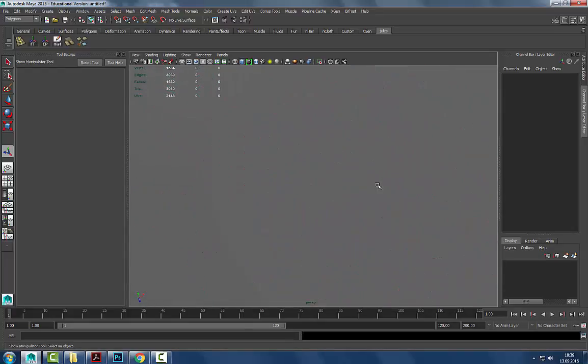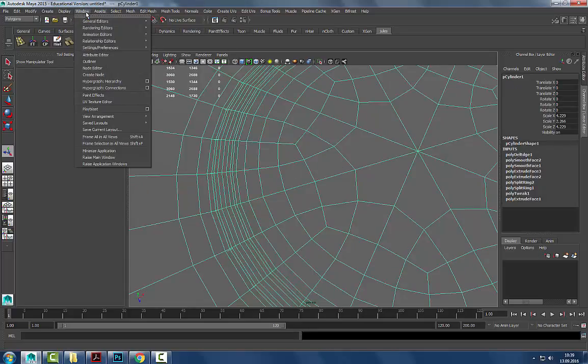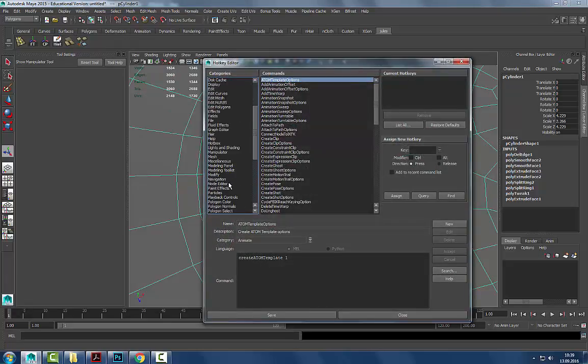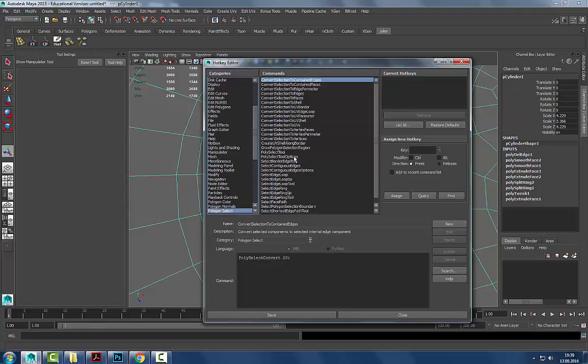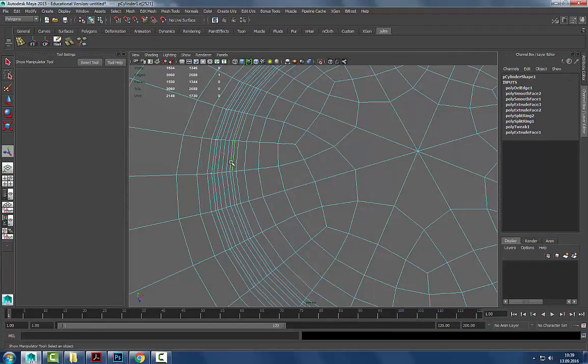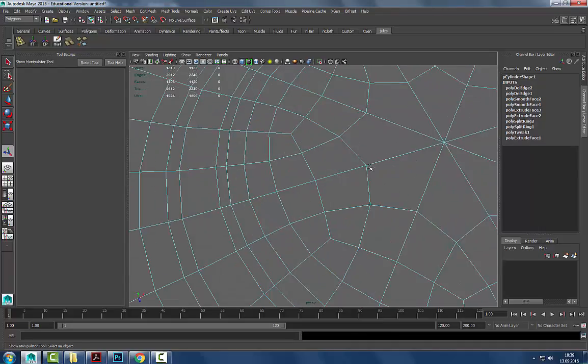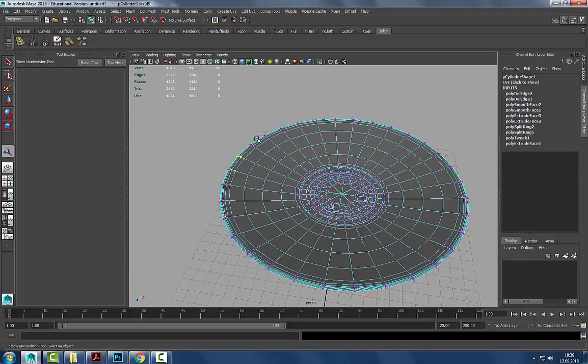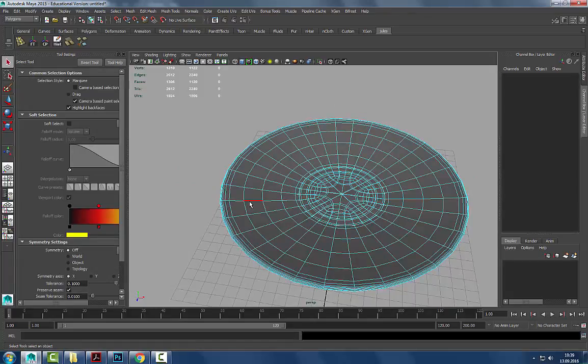This is totally nuts. So then all right, let's go to the hotkey editor, and then select, where is it, Polygon select. Yes, select edge loop. I'm going to do that on Control L. So now I have a hotkey. So if I do some of these, get rid of all these, I don't need the Control L, Control backspace. So you see what I'm saying? This needs to be fixed, but whatever. But now I have enough this way, but I'm cleaning up the ones that are superfluous because they just happen to be introduced when I did the smooth.